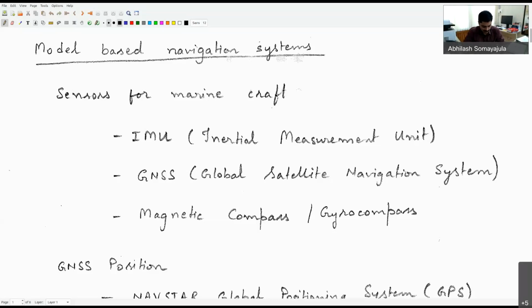Now, figuring out sensors and Kalman filters for sensors and having a complete state vector estimation for the filters itself is a topic of its own. So we are not going to embark on that purely or completely in the few lectures that we have left. But our target will be to understand that as measurements are coming in, how to formulate the best state of the vehicle. And in case there are lapses in measurements, so let's say that some sensor malfunctions and we are not getting the output from the sensor, how to account for that and still be able to figure out what is the current state of the vehicle based on a mathematical model.